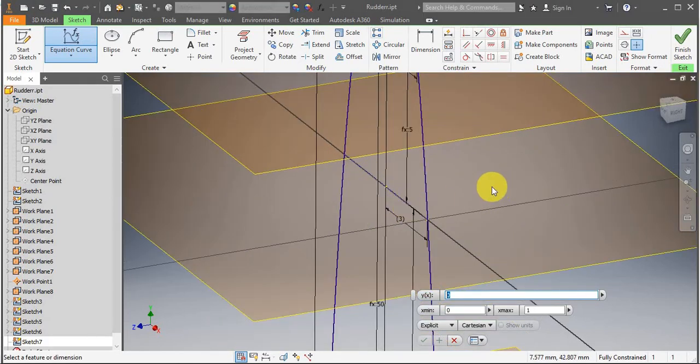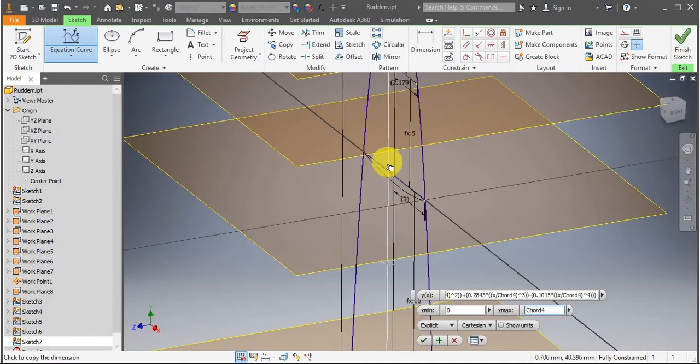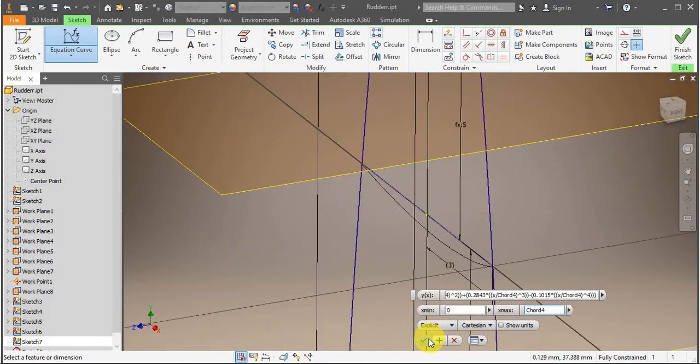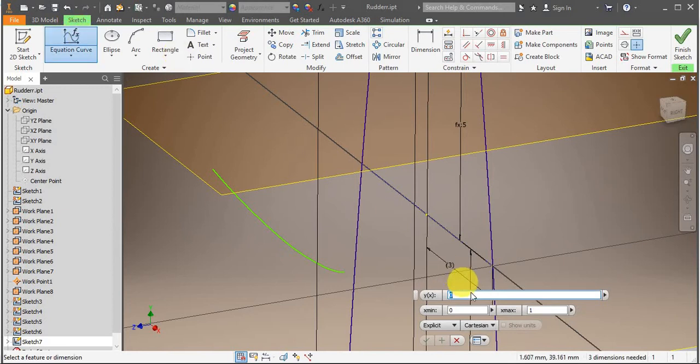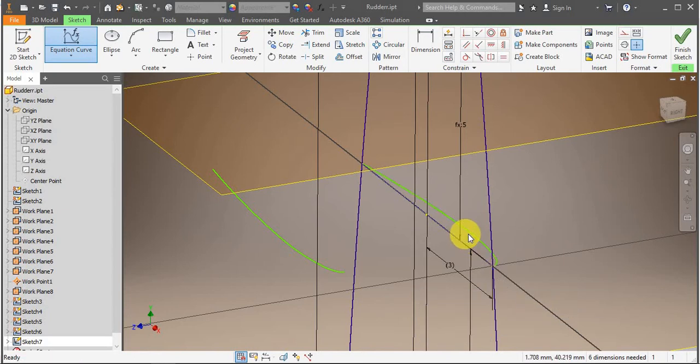Oh, I know why. I know the reason why it's adding that constant constraint. It is because if you reference this geometry first, you will place it right there. So we'll reference the geometry after. Minus 4. Check geometry. Now I'll add my constraints.